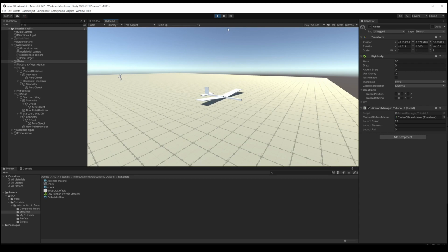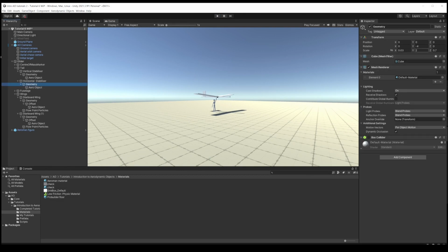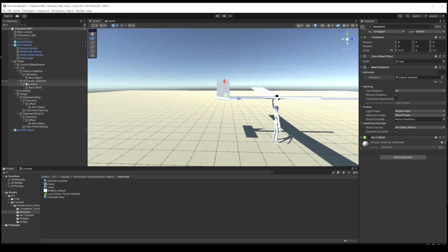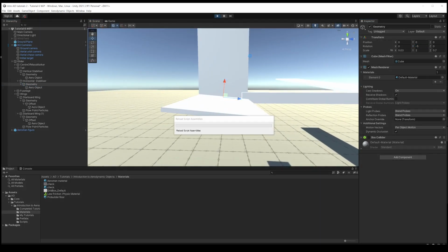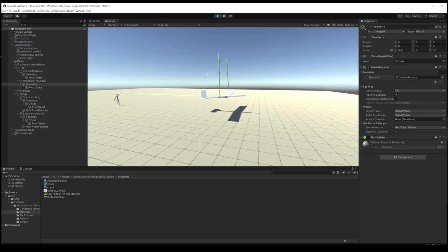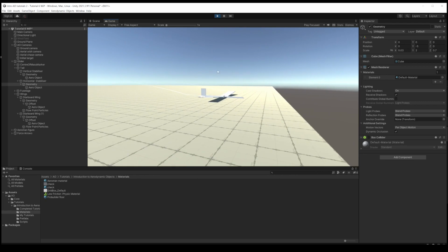It's coming down in a steady fashion. What we could try there is we just give a little bit more elevator. Tailplane is now set at a slightly larger angle. Okay, so that's proper flying. That's brilliant.